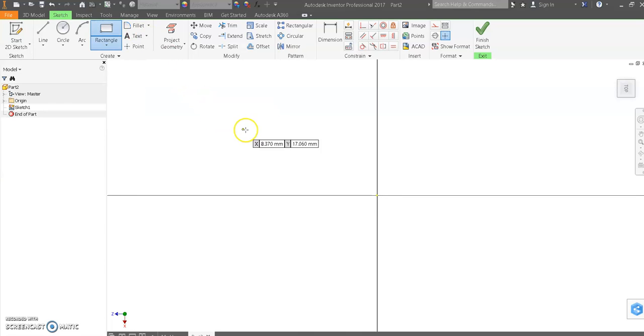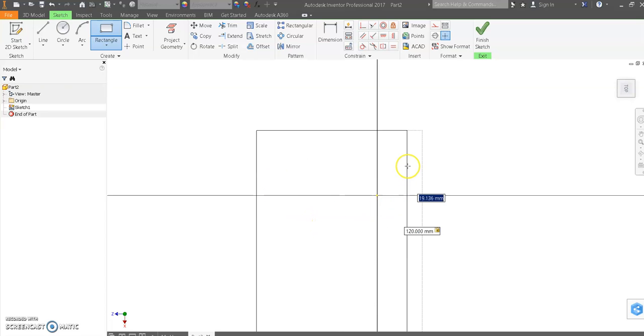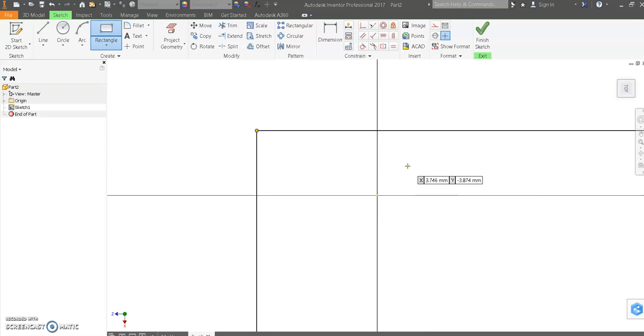I'm going to show you two ways to draw things and add dimensions. One is where we click, and then using the keyboard, we type in the dimensions, so 120. Then I use the tab key, which is the key above caps lock with two little arrows on, and that jumps from one box to the next. As you can see, it jumps from this box to this box. Now I can add the dimensions there, and then I press return, and I've got that drawing.